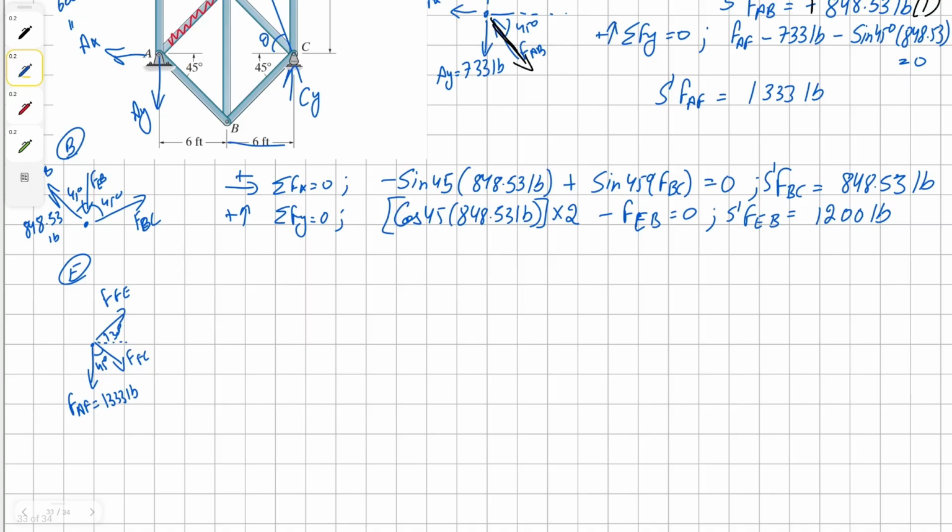So let's sum the forces in x direction. Find our solution for FC and FE. We can have horizontal component of force FE and FC. Since we have two unknowns, we're going to solve for one, and in this case I'm simply going to solve for FE, and we get a solution as 0.816 times force FC.